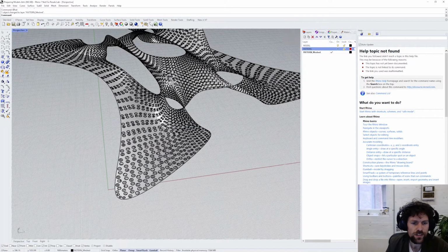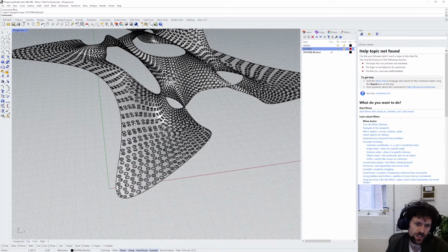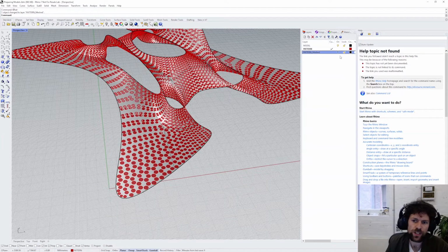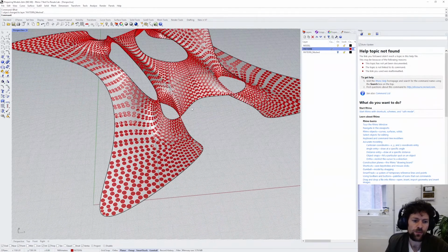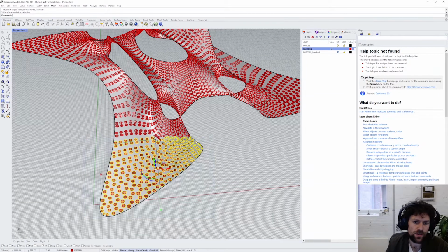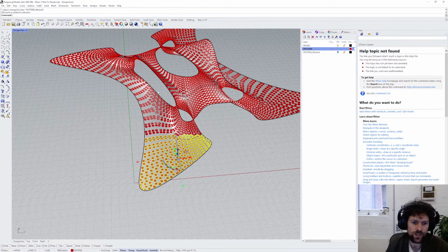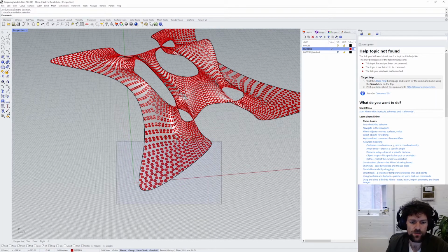If this is the case, it can be useful to just render each one of these objects as line work, which is also possible by duplicating edges in Rhino. So we can get some of these circles, for instance. Generally speaking, I wouldn't recommend trying to convert all of these circles to edges all at once, just because you may end up swapping one problem with another where you're creating a huge amount of curve geometry rather than surface geometry. But to demonstrate how this works, you can select the objects that you want to extract edges from.